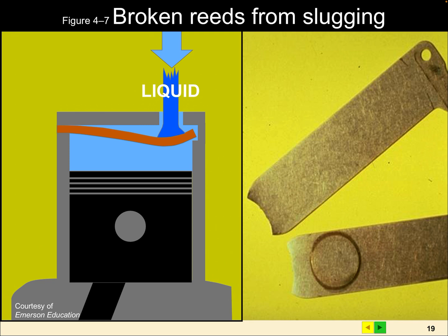Now, one of the other things that we can touch on a little bit is compressors. One of the key things is that in the event some liquid refrigerant makes its way into a piston or into a compressor, the damage is catastrophic. It can break valves. These are two images of reed valves, and you'll notice that normally this should come out all the way around here, and what happened is the reed valve has sheared off.